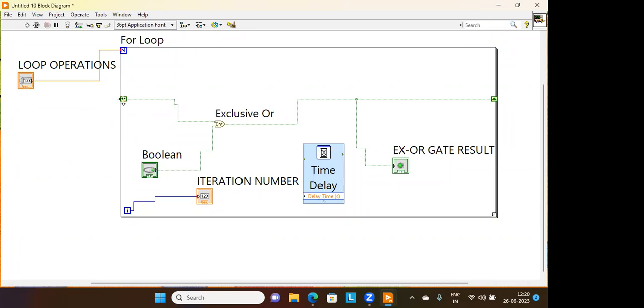Here there is one shift register on the left, one shift register on the right. Now you can drag and drop these shift registers from the bottom. Move your cursor, point towards the bottom of the down arrow that you see, just move your cursor over there and stretch it, expand it from the bottom. You see that multiple shift registers can be generated. I have generated 1, 2, 3, 4, 5, 6, multiple shift registers.